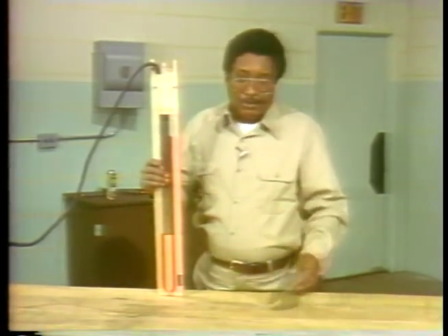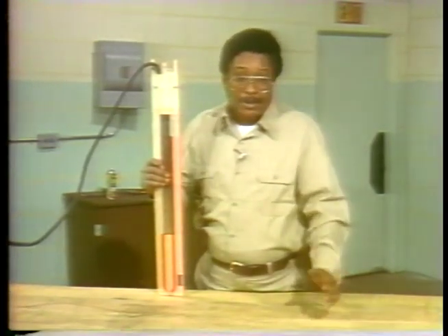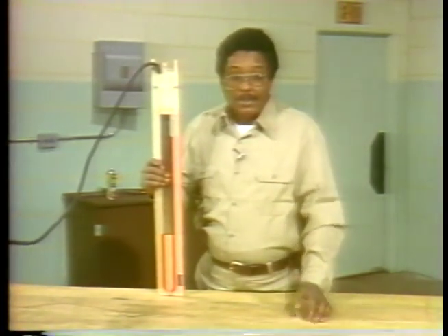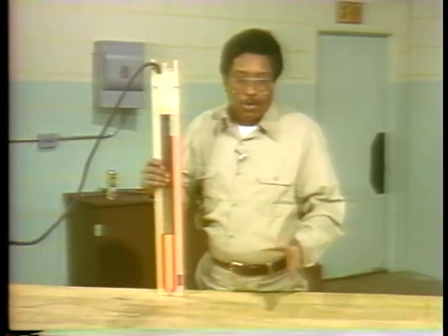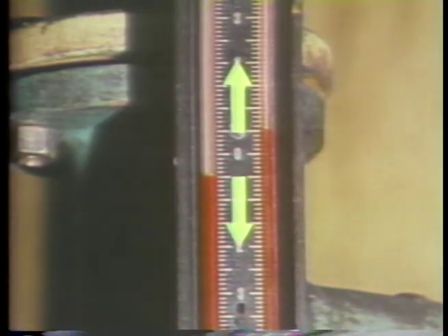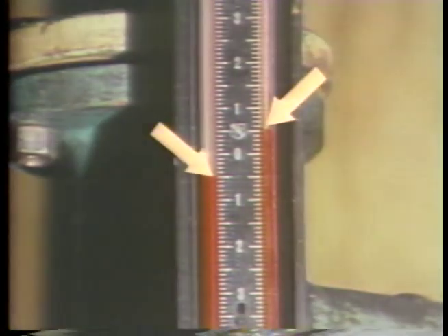Now, it won't be necessary for you to carry a ruler around with you to take readings from manometers in the plant, because there is usually a scale marked off on or near the column of liquid. In this example of a manometer connected to a main lube oil tank, 0 is marked on the scale at the point where both ends of the water column will be when the manometer is under an equal pressure. The scale progresses both above and below 0 and is measured in inches. To read the scale, you simply add the reading from both ends of the water column.